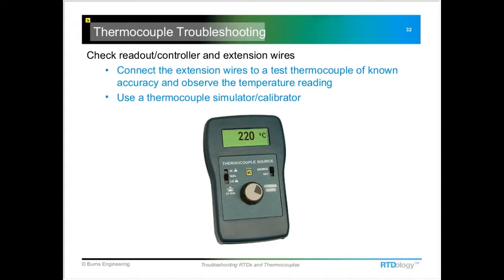And for air temperature, if you're just reading ambient temperature, an exposed junction thermocouple would probably give you the best response time and the most accurate measurement.